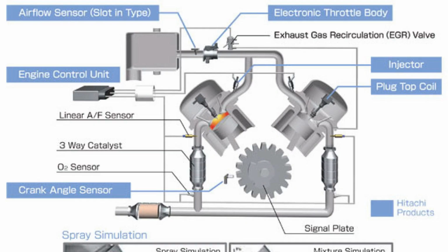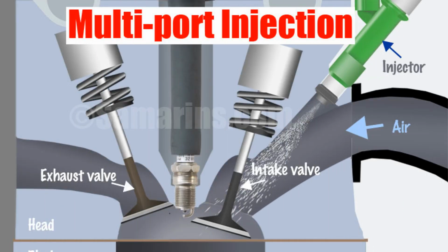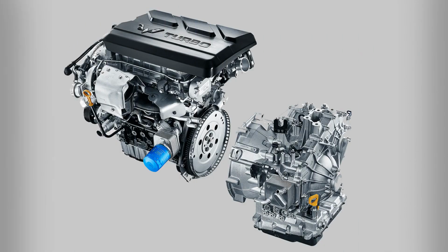Fundamentals of the operating principle. Requirements that the fuel-air mixture of a gasoline engine must meet: be in a gaseous state. In other words, for efficient combustion, the gasoline must be completely vaporized before the fuel-air mixture ignites. To be homogeneous. The gaseous state promotes good mixing of the fuel with the oxidizer, oxygen, which is in the air. If mixing is uneven, in areas with a lot of oxidizer the risk of detonation increases. In areas with significant over-enrichment, gasoline will not burn completely, resulting in lower engine efficiency. The amount of fuel supplied must match the mass of air entering the cylinders.